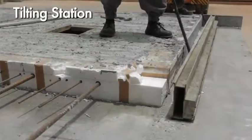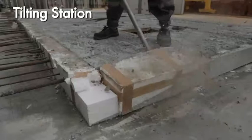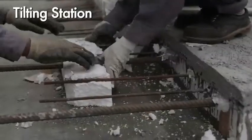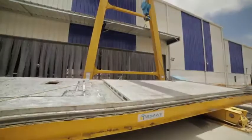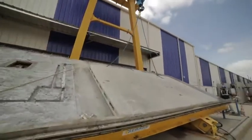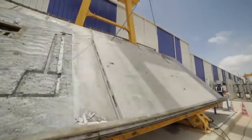Tilting station. All the shear keys and thermocol inside the module box sockets must be removed before shifting the panels to the storage yard. Next, the panels are shifted to the storage yard. Demolded elements must be numbered and labeled for easy identification.